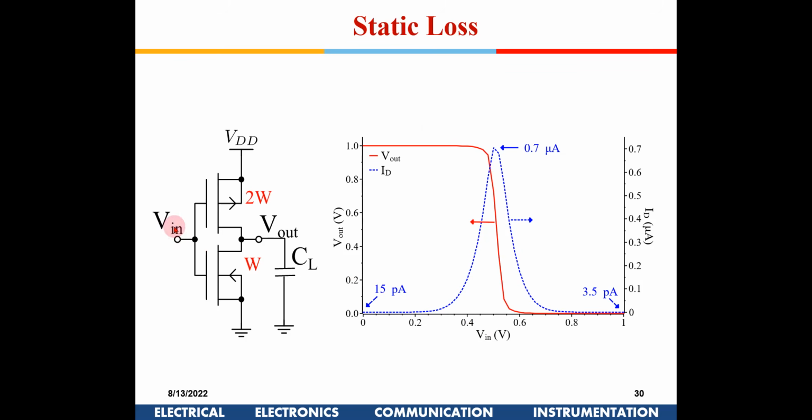Static current is because even if you are not applying gate voltage, the threshold voltage is very low, and at room temperature there will be some minority carriers. Since the threshold voltage is very low, you don't have a very strong reverse biased PN junction between the source, the drain and the channel region. We saw that initially in our first class.